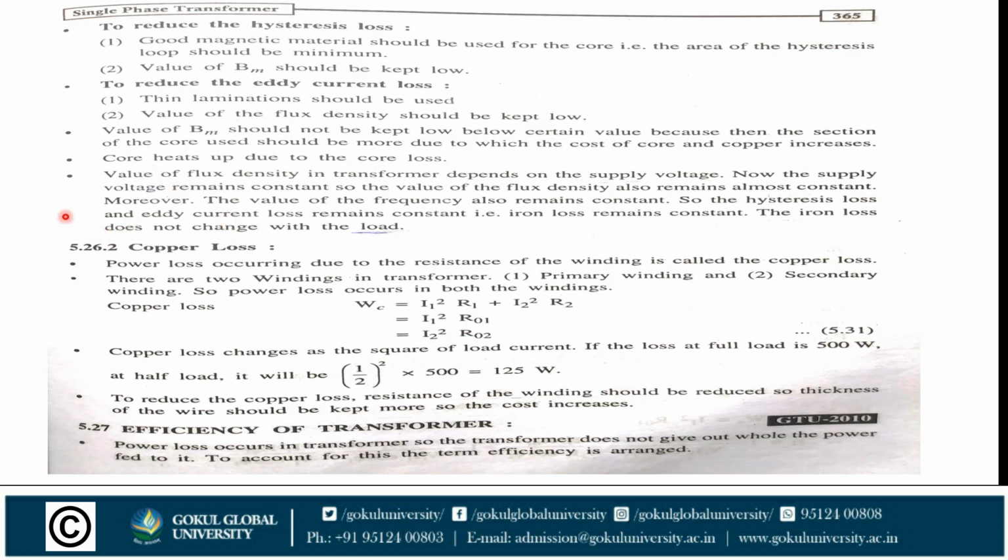Now the value of the flux density in a transformer depends on the supply voltage. Since the supply voltage remains constant, the value of the flux density also remains constant. The frequency also remains constant, so the hysteresis loss and eddy current loss remain constant, meaning iron loss remains constant. The iron loss does not change with the load; it is totally dependent on the frequency.